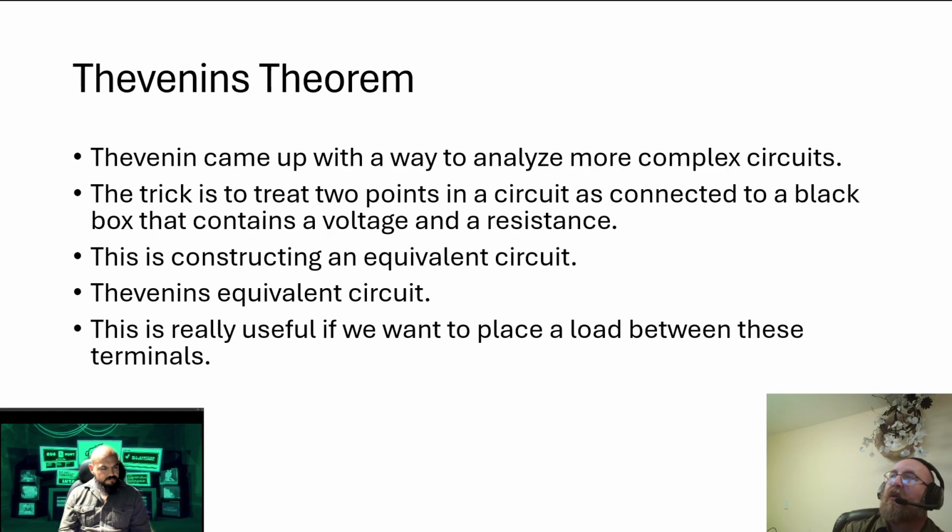Sounds like a plan. But before we get to that, I just want to tee up this ball. I want to give us what Thevenin's theorem is. Thevenin's theorem is a way to analyze more complex circuits, and it's basically a trick that treats your circuit as a black box, and there's 2 points that you're measuring from.